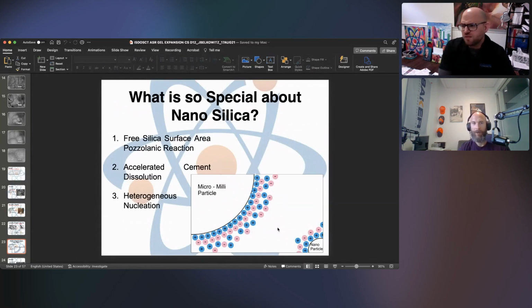And with Brian, if you read his paper, he wasn't using it to enhance concrete. He was using it as a viscosity modifying agent. Turns out it increased the density to the point that it wasn't just water permeability, it was wave attenuation of nuclear payload or blast loads that were changed to, as the title insinuates, the rock matching grout, as opposed to the xanthan gums or dextroses or celluloses that we had used in the past. And of course, with that, there was a strength development too, but that's something we can get into here in a little bit.